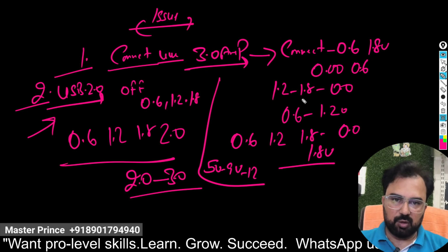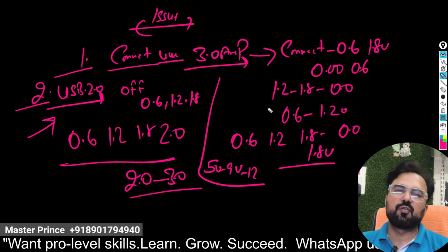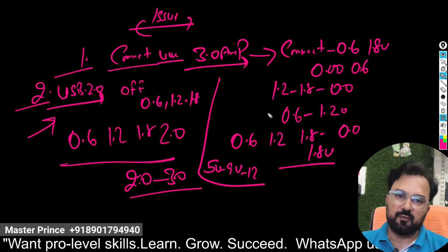That's why, when the phone is turned on, it shows connect, disconnect, connect and disconnect. But when the phone is turned off, it stays on a low ampere charge, I mean in normal mode, not turning on fast charging, because the communication is also off.